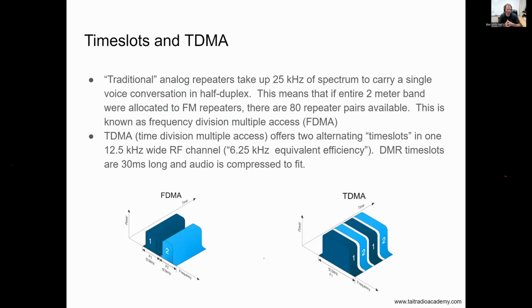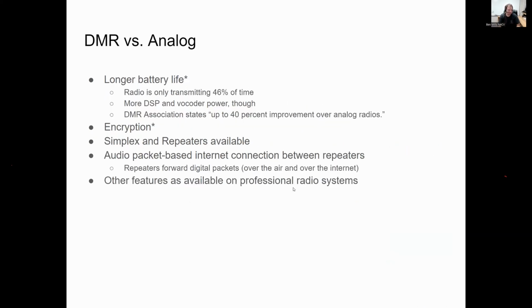And as I mentioned, it went from 25 kilohertz down to 12.5 kilohertz bandwidth. So what these commercial vendors were seeing is their wideband FM channel, we could now pack two separate DMR systems, and each of those would carry two talk groups. So we'd actually quadrupled the amount of channels we could carry on our repeaters in the same bandwidth. Just something to consider from that.